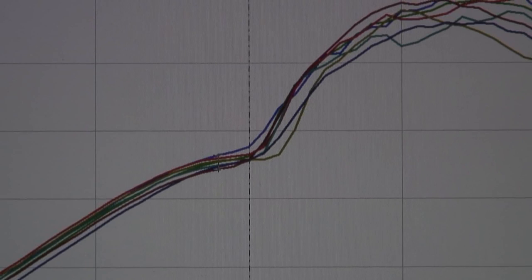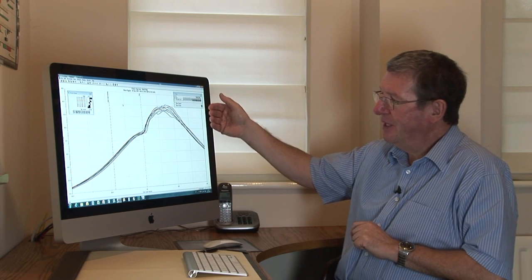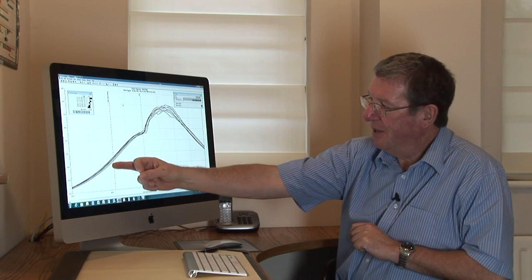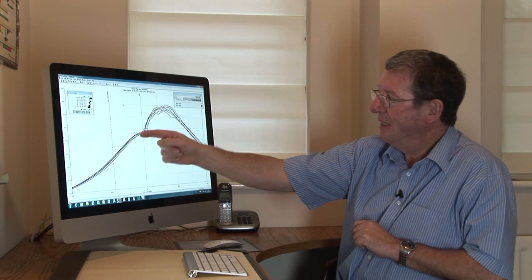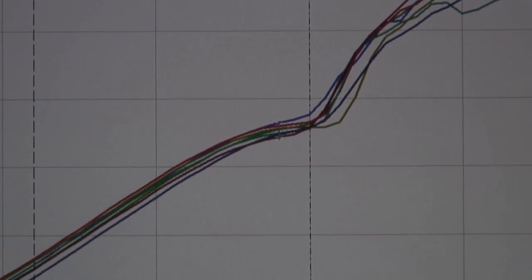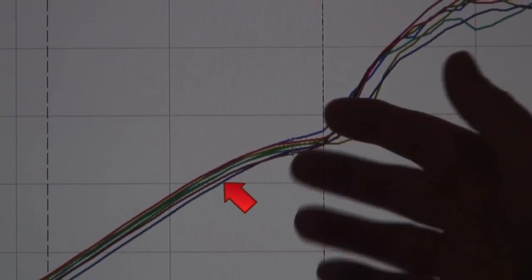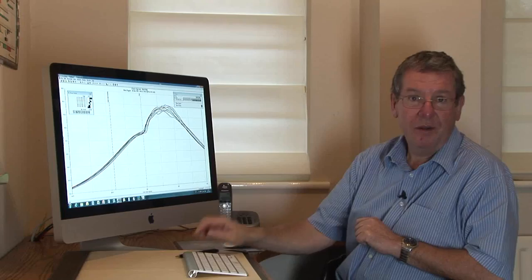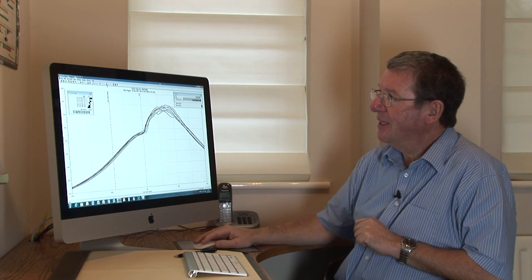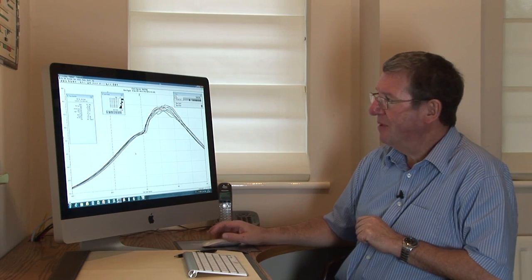The next step is to look for pre-ignition, and I'm going back to displaying just the A bank. And in this, to find pre-ignition, if you examine the order in which the graphs appear at about -20 degrees before top dead center, and then look at them again where you evaluated the compression, which is just before the ignition point. In this case we can see one graph which is low at -20 degrees but improves in pressure before the ignition points, and that can only happen by fuel burning in the cylinder, which can come from a leaking injector needle. So we need to identify that cylinder and find out which one it is. That turns out to be cylinder A6 with pre-ignition.